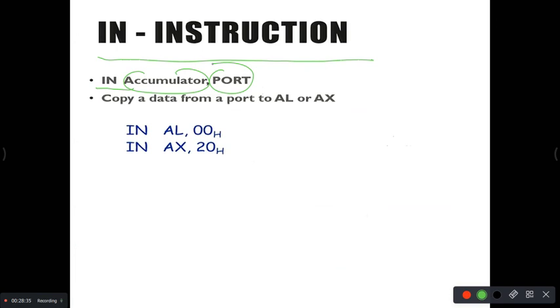Remember this. Your microprocessor data lines are not directly connected to the IO device. It is connected through another device called the programmable peripheral interface, which has multiple ports that can be programmed to have access through an address called the port address.